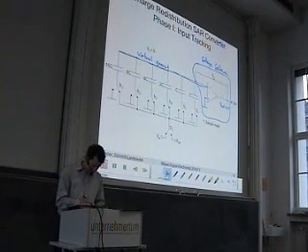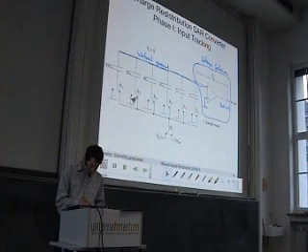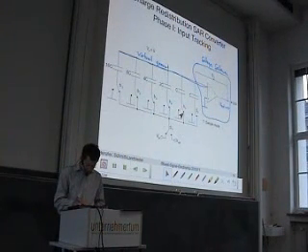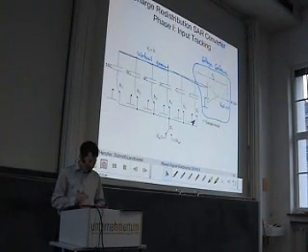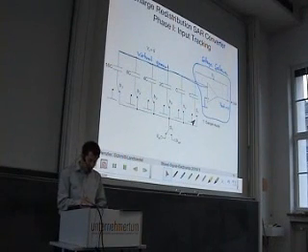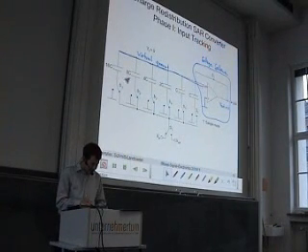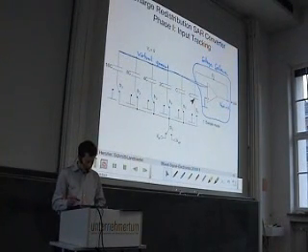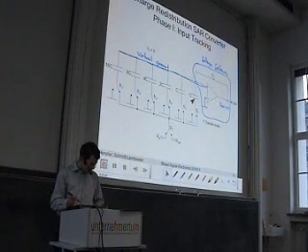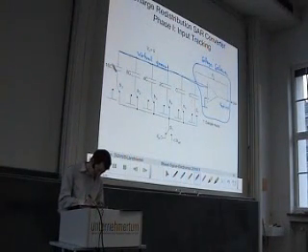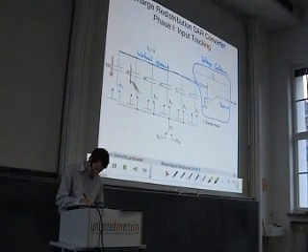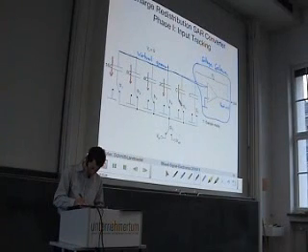We connect via these switches all these caps to the input signal. So up here at this plate we have the virtual ground. At the other plate of the caps we have the input signal. So the voltage across all caps is the same. They're all in parallel.